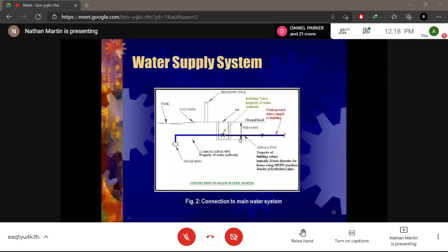So they'll come to your meter. Now this is really giving you an example of the depth at which you need to bury your pipes. A lot of times when you go to facilities and so forth, you realize if it's not properly done, you're actually seeing your underground piping systems. You should not be able to see your underground piping system.